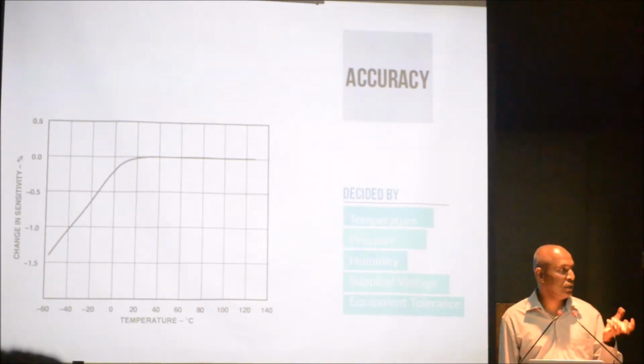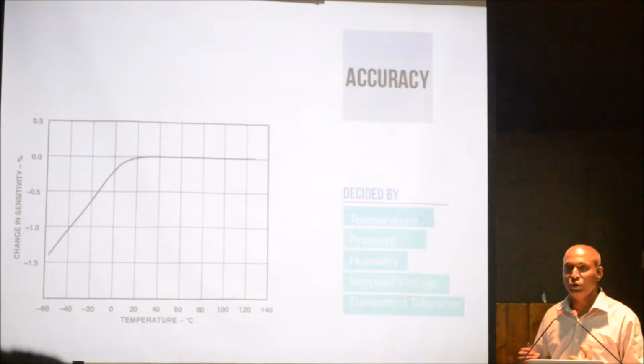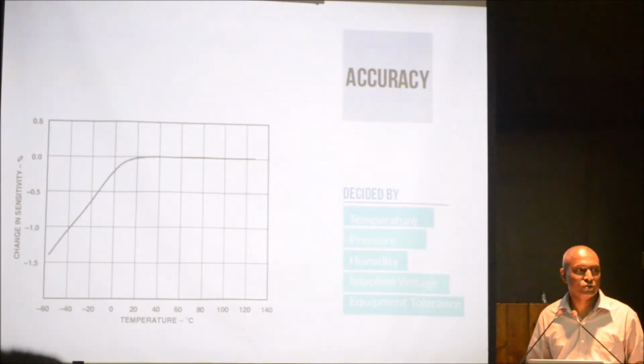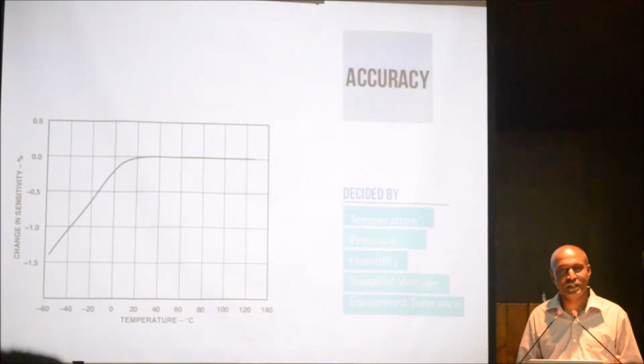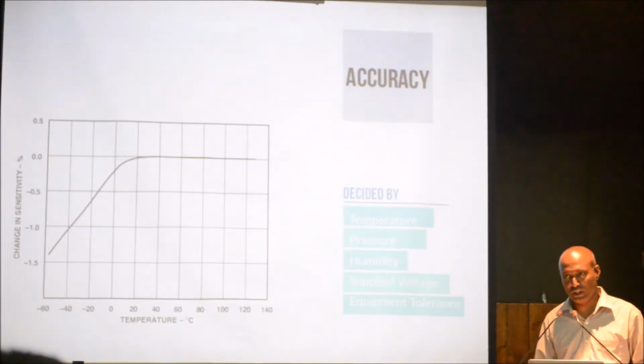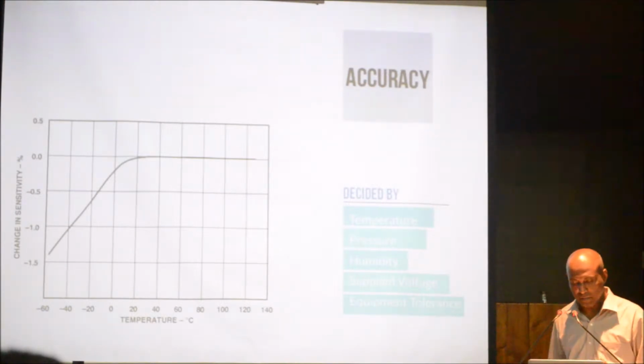For instance, if your sensor is battery powered, you need to know how long it would work. When battery power reduces, how would it react? What's the range? It should work for low battery power as well, and it should indicate whether the battery is low or not. Those are very important things that we need to consider.